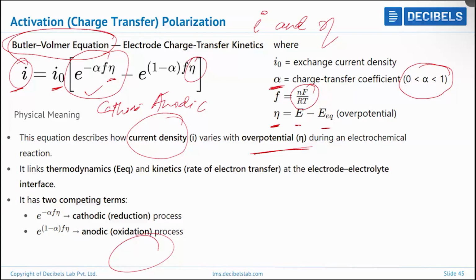The main demerit, the challenging task for the solid state battery, is the solid electrolyte being used between the anode and cathode, where the lithium ion diffusion coefficient D_Li+, which I have discussed in the Nernst-Planck equation, is actually very low, because the lithium ion has to percolate in the solid matrix only. But in this battery, the lithium ion can swim easily in the liquid electrolyte compared to solid.